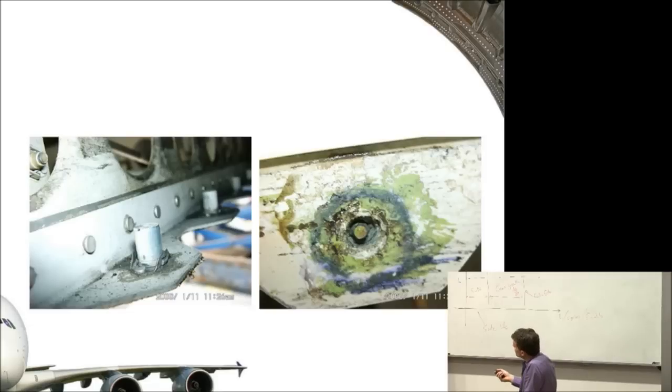Okay, and some examples here where you've had a steel lug for taking a steel pin, bolted onto an aluminium bracket, and they haven't inspected for corrosion enough, and when they've taken the steel pin off, there's a lot of corrosion in the aluminium underneath. And so generally from a structural perspective, we're trying to avoid mixing and matching metals.